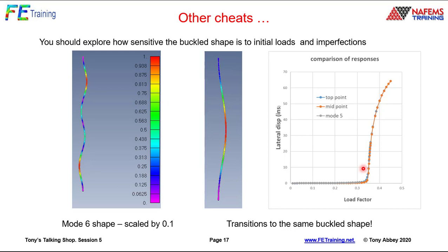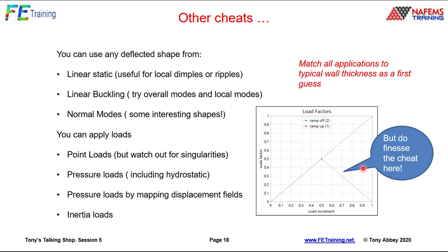They're not always going to be like that. Thin wall shells in particular, with very little supporting edge stiffness, like you might get, for example, in a rib, in part of an aircraft skin structure, can be quite prone to this kind of level of imperfection, which means we've got to do a lot of work to study the sensitivity of that type of structure.